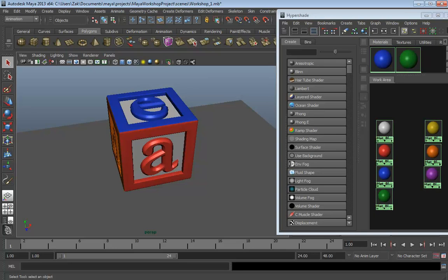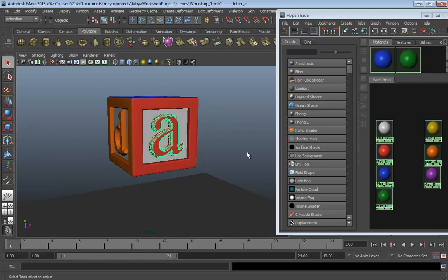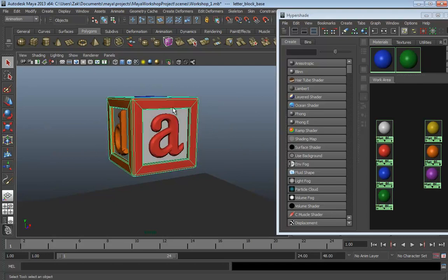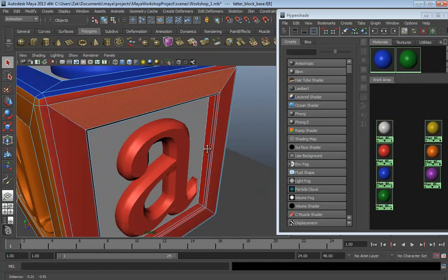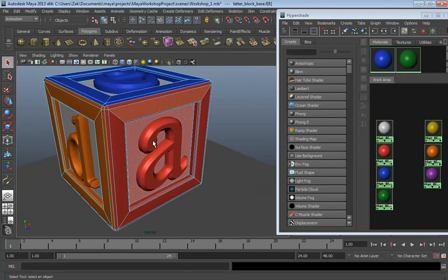MMO Dust just asked if there was a way to spin around the cursor as opposed to the viewport. Not that I'm aware, but do keep in mind that you can select an object or a component such as a face and tap the F key and frame up on it, and then you're rotating around that one thing, and that's kind of nice.